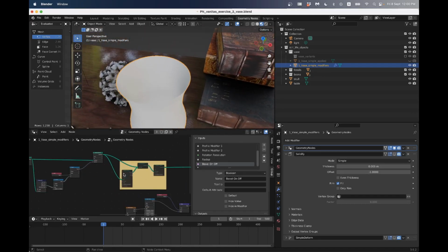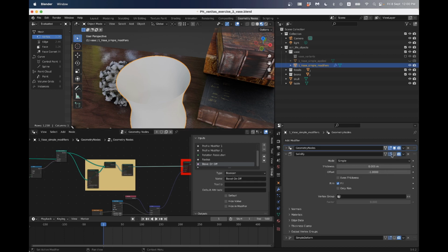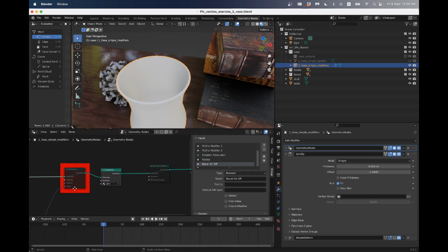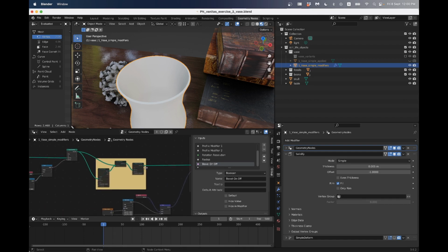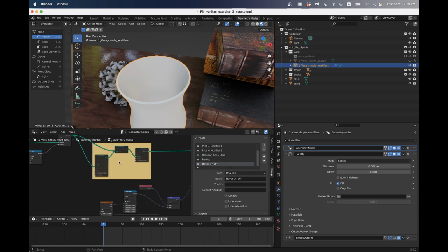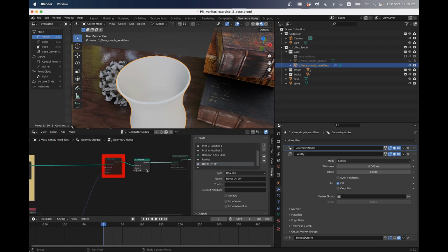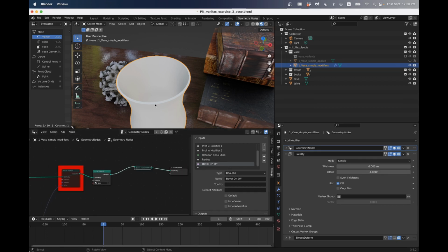And I think I also hid this extrude and join section here, and I simply used my solidify modifier here, and I also turned off some of these shade smooth and so on things here. I didn't really need them. So we can check in class if there's any issues there, but I've turned off this section here, the join and merge by distance, and I also turned off my set position and set the shade smooth.